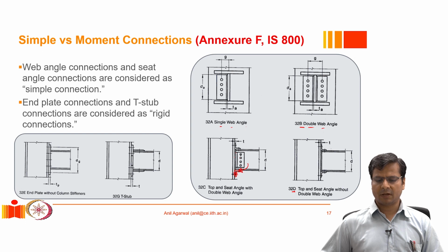And we typically have a couple of bolts here or a deep weld here to connect this angle to the column. Sometimes this angle can even be stiffened. We may put a stiffener inside this angle to help it resist the load more effectively. As you might realize, let me zoom into it a little bit. This is the angle geometry, and the beam's bottom flange is sitting somewhere here like this, right?